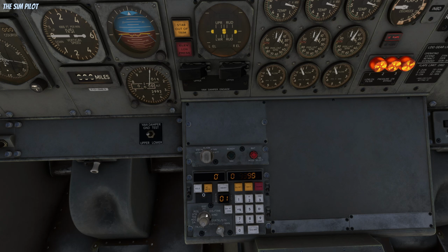If you scroll the switch to the desired track status, it's going to start displaying a number. This is an index number, so don't expect this to change in certain time, like minutes, seconds. But this is going to start going down, and when you see 0.5, that means your INS is aligned. This is realistic alignment, so it's going to take some time. If you don't want to wait, you can click the ready light, and that's instant alignment, so know that too.